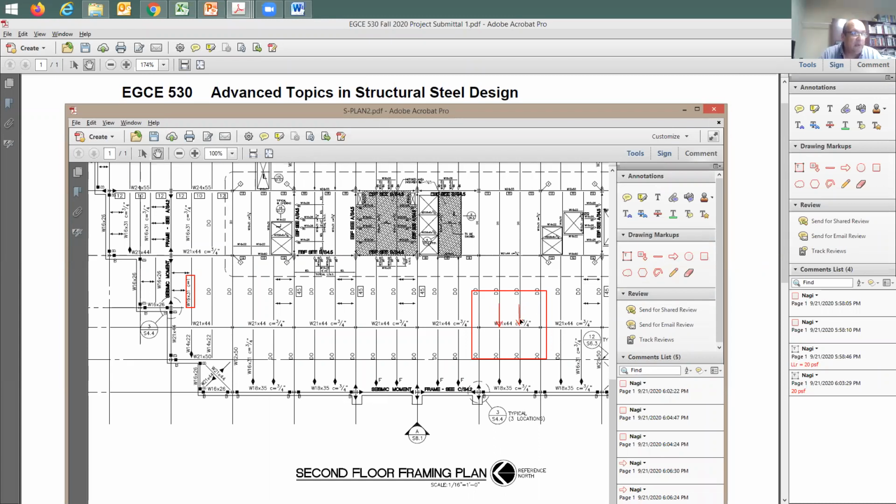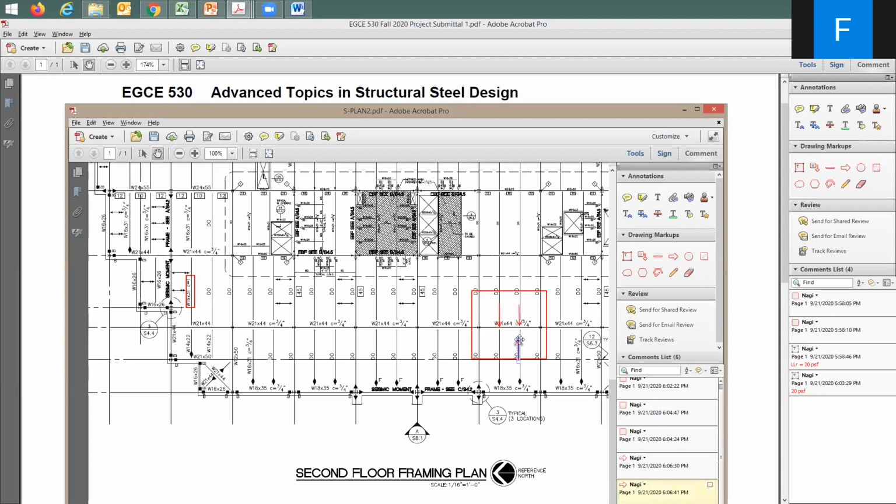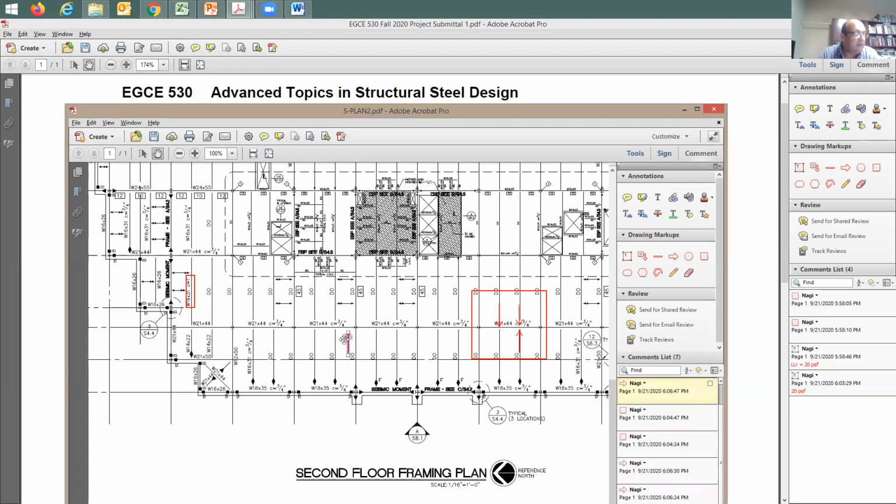Yes, you're going to have 2 point loads, but don't forget that you're going to have a point load coming from this beam, another point load coming from this beam, right? It's going to be like this. Does it make sense? Yeah, thank you. So you need to do the reaction from each side, the reaction in terms of dead load and live load, right? And then you need to design them or put them this way to be able to work on this girder design. Okay, thank you. No problem. Any other questions?